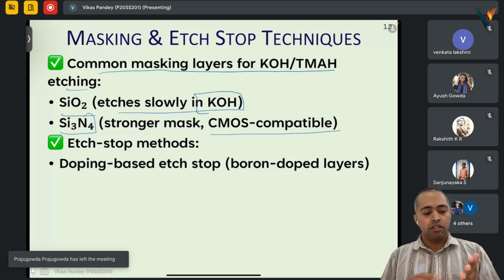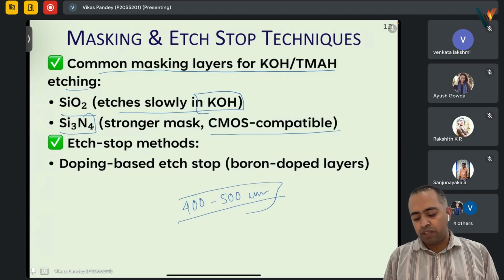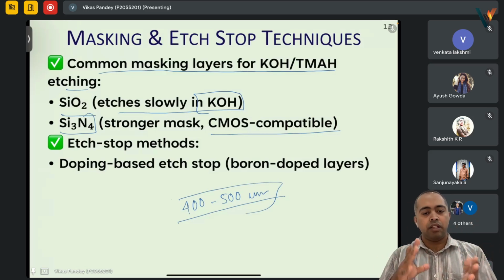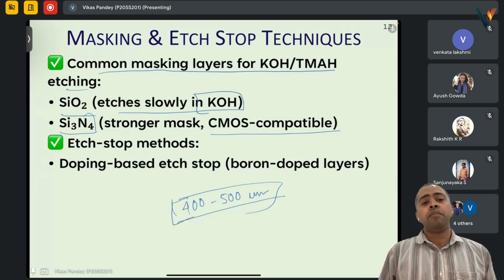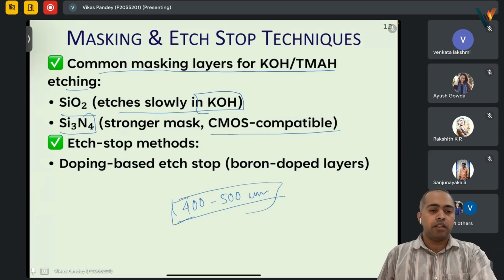Physical Teflon-based structures can be used for very big holes, say 400 to 500 micrometer in size. In that case, it is just kept and mounted over the silicon wafer. If the sizes are smaller, then we go for lithography, which we will see in the next section.